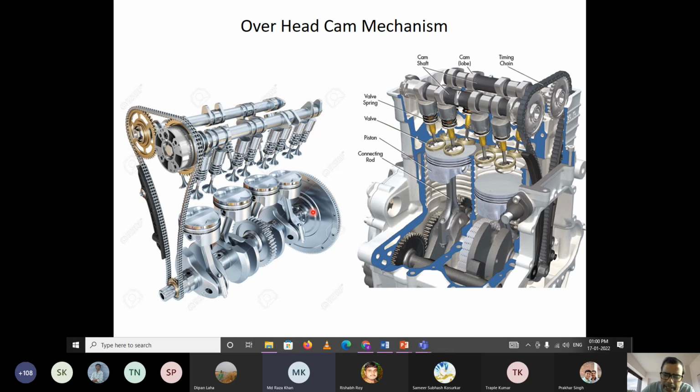If it is a single cylinder engine or double cylinder engine, then we have a flywheel. In a single cylinder engine, the flywheel acts as the driving force. It will store the kinetic energy and then release it later on. That is the way it takes care of the driving force of the remaining cylinders in which the combustion stroke is not going on.